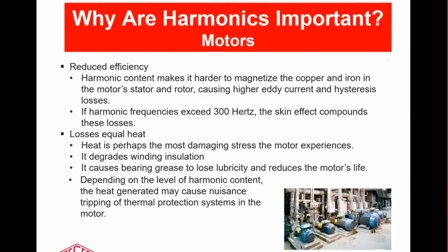Okay, so why are they important? They're important because they cause problems. One of the areas where they cause a lot of problems is in motors. They reduce the efficiency of the motors because they make it harder to magnetize the iron in the motor stator and rotor, and they cause eddy currents and hysteresis losses.